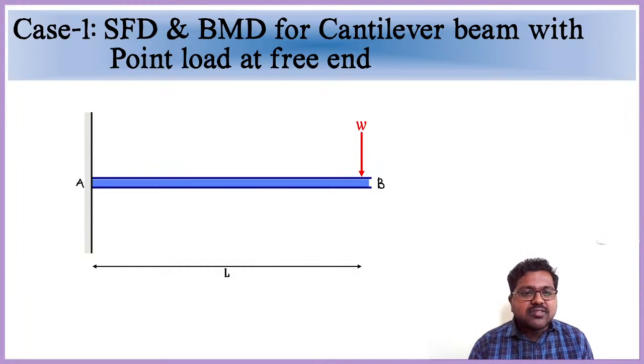See, the support reactions means here we are having A. At this A, this is a fixed support. We already know at fixed supports, both translations in X direction and Y direction and rotation around A, all these three are restricted. So both translations and rotation are restricted here. So we are having reactions in all three. Let us see first, W is acting upwards.